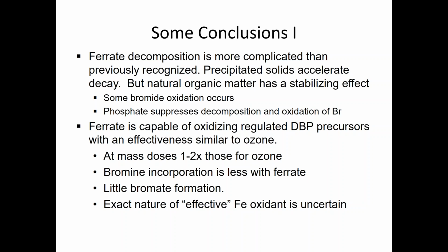Okay, so I'm going to stop my presentation of data here and just go over some conclusions and what we've learned so far. First is that ferrate decomposition is substantially more complicated than we first thought. Even though we've been studying ferrate in the laboratory for 30 years, once we start looking at real waters and understanding how the real waters differ from laboratory prepared waters, we recognize that there's this issue of precipitation of solids that accelerates the decay. And that can be good or bad, but one of the good features is that natural organic matter slows it down.